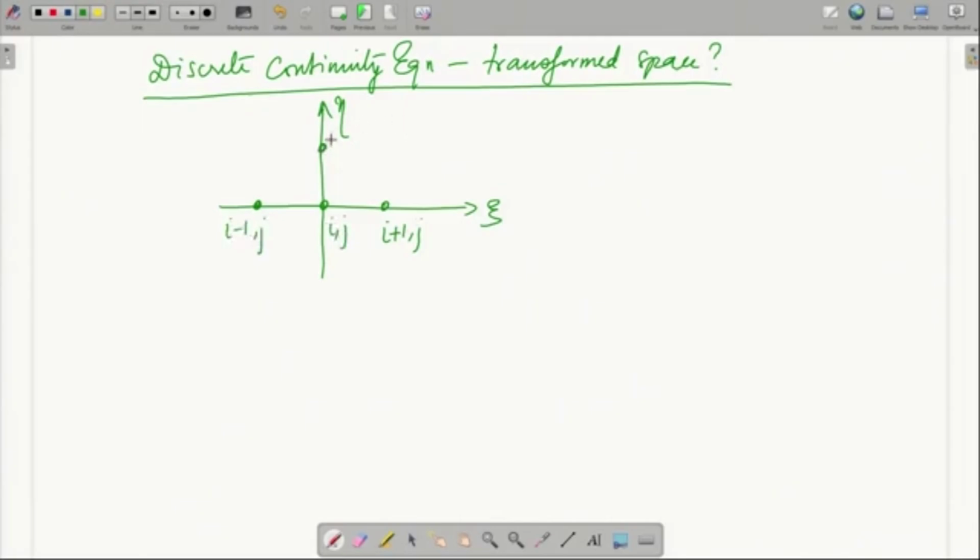Remember that these grid locations, though they are in a regular manner over here in the computational plane, they are irregularly displaced in the physical plane, but nevertheless the mapping is identical. The I j which we see in a computational domain exactly maps with a corresponding point in the physical plane, where a particular xi line and a particular eta line has intersected.